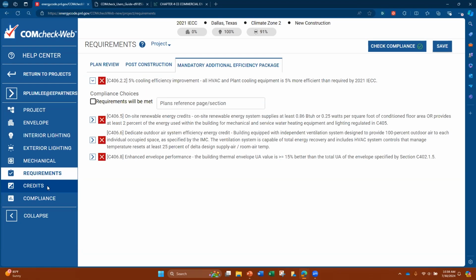It's not that easy in commercial, and you're mostly doing a visual verification of A, the product being installed, B, is it following manufacturer's instruction detail, and C, did they actually do that and not destroy it during construction. One person did the air barrier, house wrap, or a roll-on membrane. They've done that, but now you've got a plumber that's come in to correct some things and they've punched holes through it. You've got to verify that to make sure it's upholding. And you're not able to verify it at final with the blower door in most cases.